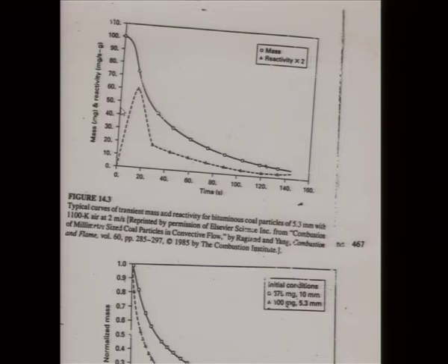And small particle. So the particle is getting heated at a very high rate. So it's not just the temperature, but also the heating rate which matters. If you increase the heating rate, in fact, you will get more volatile matter. That's what happened in this case. That's what, of course, is also going to happen in the pulverized coal combustion situation in a boiler.